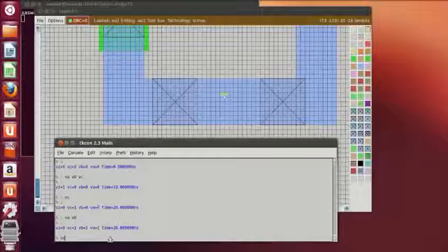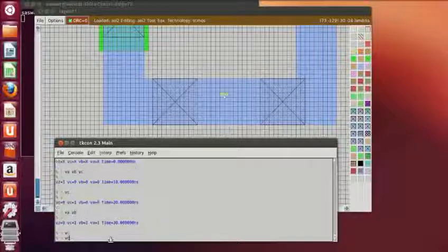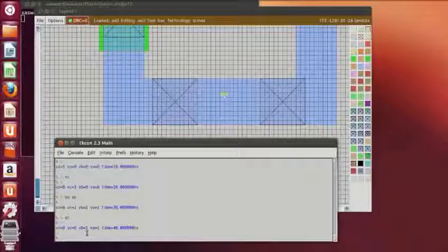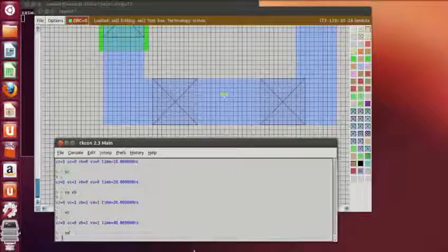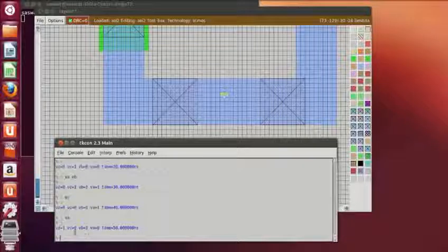If I give low value to VC, then my output will be 1. Low VC, then S. Okay, this is 0. This is the OR operation. So the output of the AND is 1 and this is 0, so the output will be 1 and invert will be 0. So have to give low value to either VA or VB and then S.